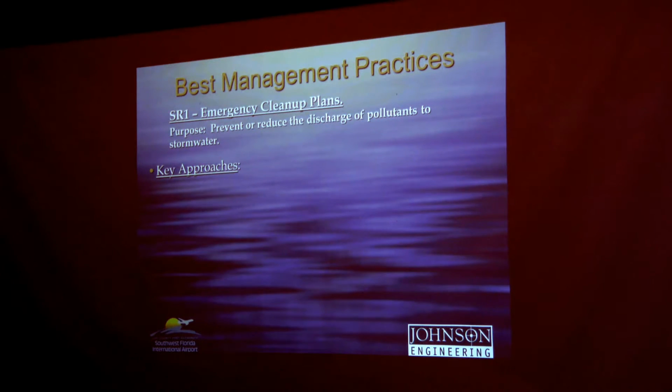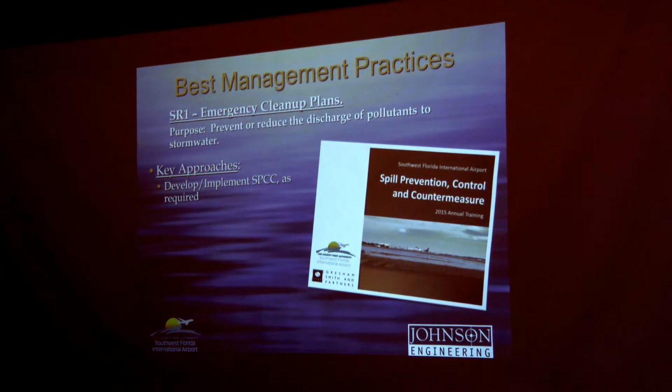That brings us into SR1, which is emergency cleanup plans. Appendix D of the SWIP provides the RSW spill response and reporting procedures. Key approaches include developing and implementing a spill prevention, control, and countermeasures plan, which we're going to have to go over a little bit later.